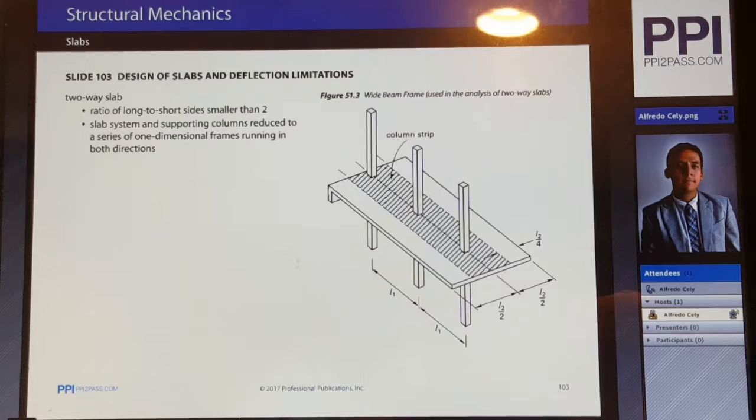It is difficult to obtain accurate estimates of deflections in two-way slabs. In practice, rather than attempting to calculate deflections accurately, two-way slabs should be sized to satisfy the minimum thickness values given in the ACI Code 318 under section 9.5.3. Since deflection calculation requires special finite element analysis, it is common practice for slab thicknesses to be above the values given in the table.